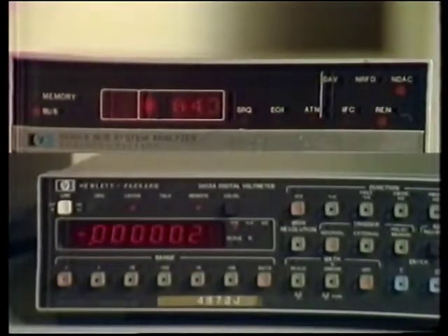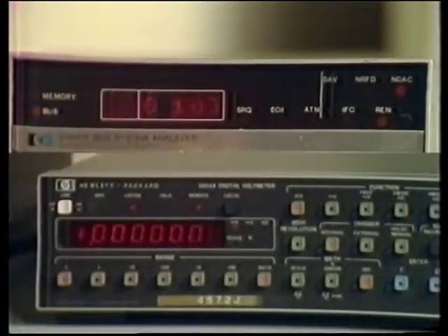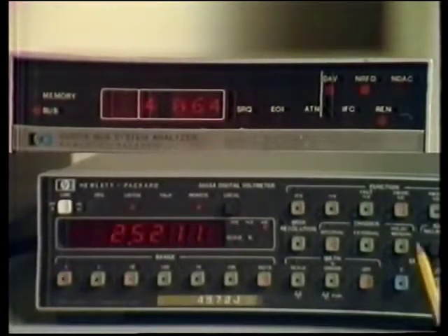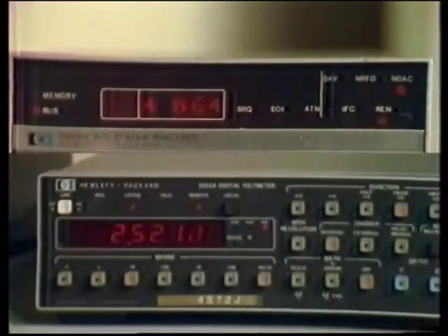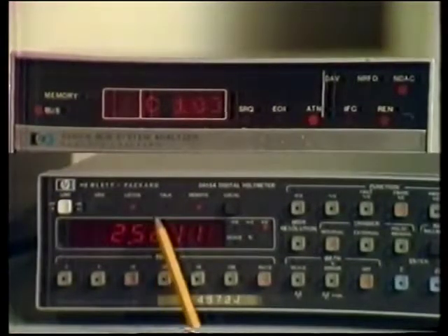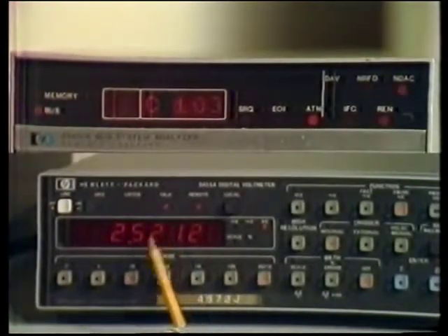Now, with attention false, that means I'm sending data to the DVM now. I'm going to send F4, which selects the resistance range. So I send an F, and then a 4. And if you look at the resistance range button, you should see the light come on now. With attention true again, I can tell the DVM to talk by sending its talk address. That's 103. So if we look at the talk light, when I send the handshake signal, now the DVM is addressed to talk.